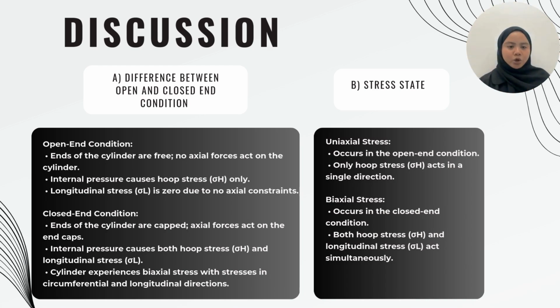Only hoop stress acts on the cylinder, making it a single-directional stress state. The biaxial state of stress is experienced in the closed-end condition. Both hoop stress and longitudinal stress act simultaneously, resulting in a biaxial stress system.